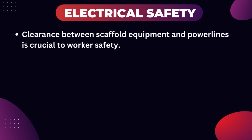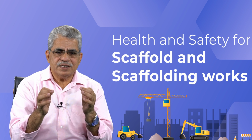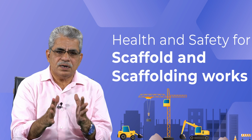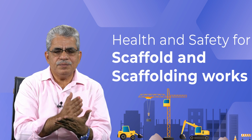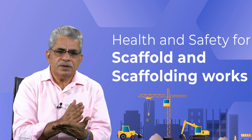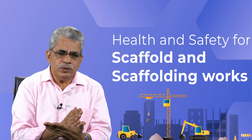The clearance between the scaffold equipment and the power lines is crucial to worker safety, because there may be chances that where work is going on and scaffold is required, there power lines are also there, and these power lines are in the open, then there may be chances that our scaffolds, which are generally metallic, made of metals basically, if these scaffolds come in contact with these power lines, there may be a big accident because of the electrocution. So what we can do?